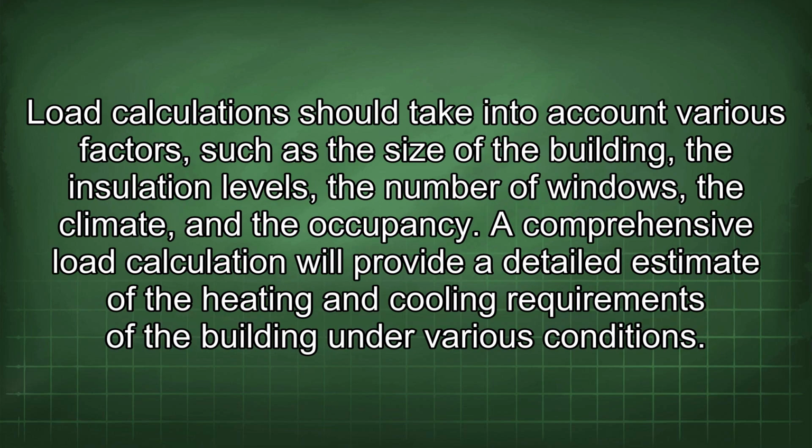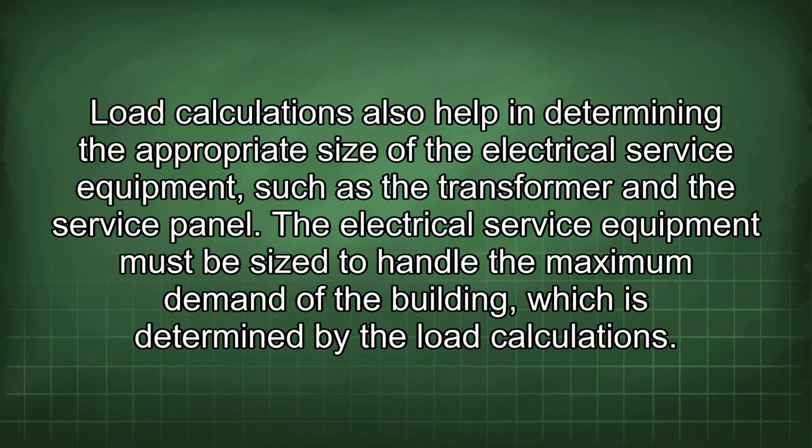Load calculations should take into account various factors, such as the size of the building, the insulation levels, the number of windows, the climate, and the occupancy. A comprehensive load calculation will provide a detailed estimate of the heating and cooling requirements of the building under various conditions.